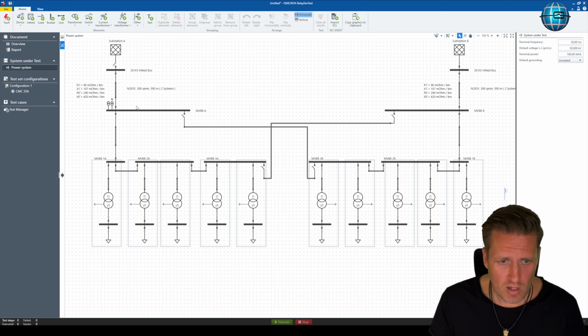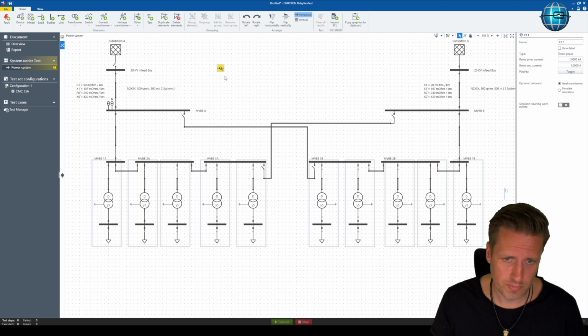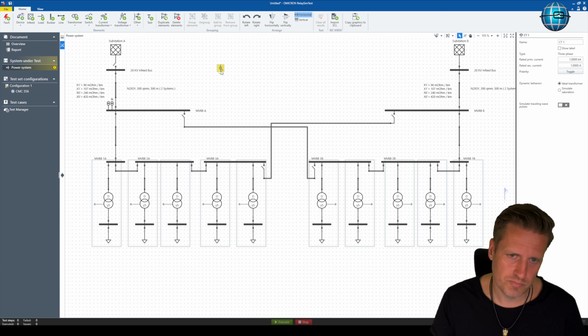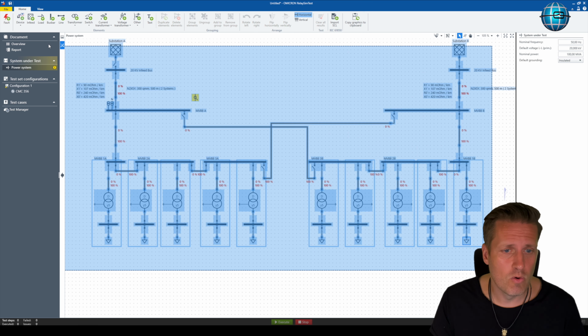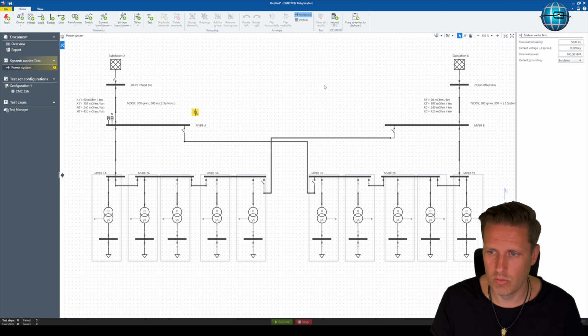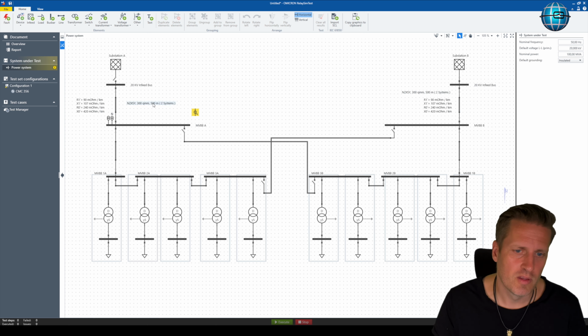Okay. And now we need current transformers. Let's take, first of all, the one for the three phases, turn it around, and you can toggle the earth, which should direct to the protected element, which is our bus bar. And now I take everything and put it a little bit down. Yeah, this is also not the best way to show it.